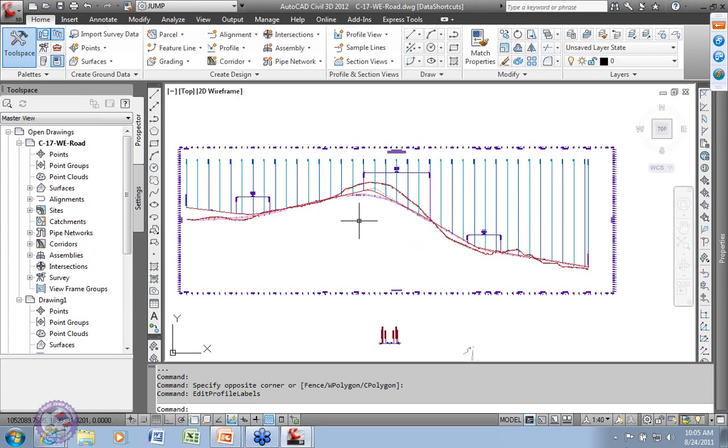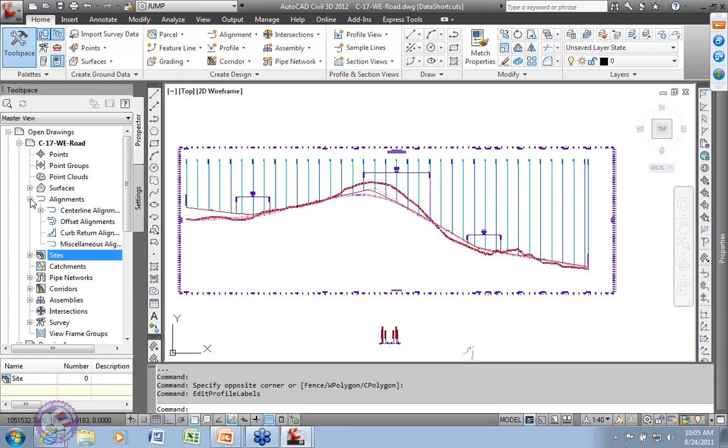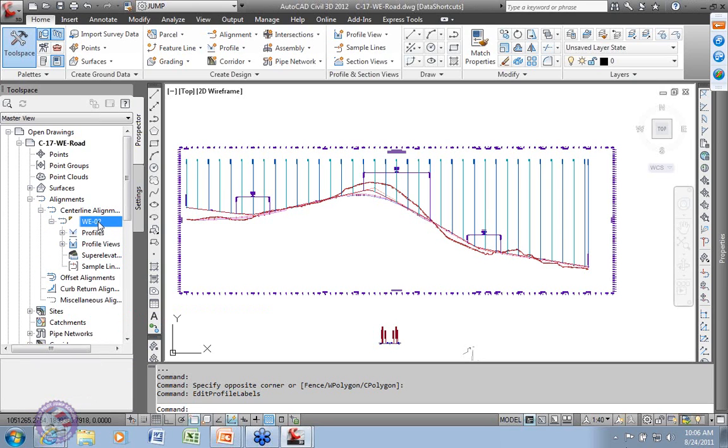And one of the things we have in Civil 3D is this idea that we have data. Over in the Prospector tab, I'm going to move a couple of things here. We have an alignment collection, and you will see, simple basic stuff, that there's no such thing as a profile collection. Right away in Civil 3D, there is this idea that a profile is collected under its alignment. So here is our major alignment, which is somewhere, maybe on the screen, maybe not even in this drawing. It happens to be in this case. And we have a whole bunch of profiles.